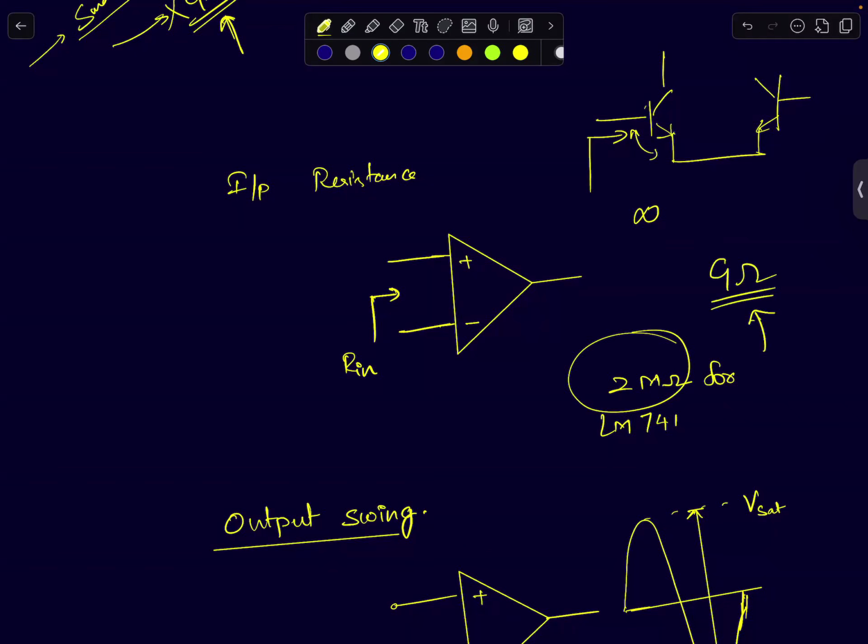Okay, because for a MOS based op amp, the input is an oxide. So it's an insulator, so it will have much higher input impedances. So for your 741 op amp that you use in the lab, it will be in the order of mega ohms. You can measure this. In fact, you can use an ammeter to try and measure this, but you have to power the op amp and measure it. So you have to be a little careful.